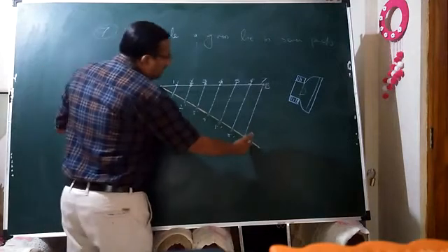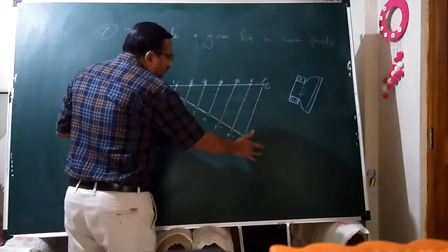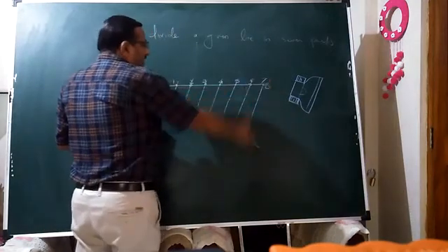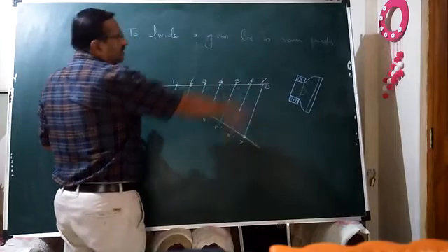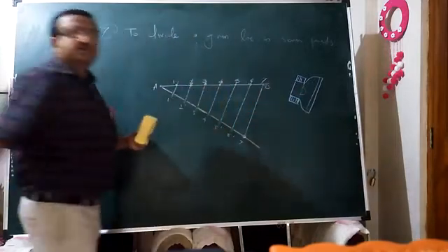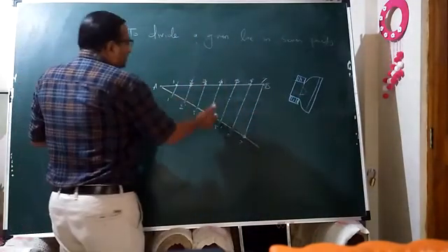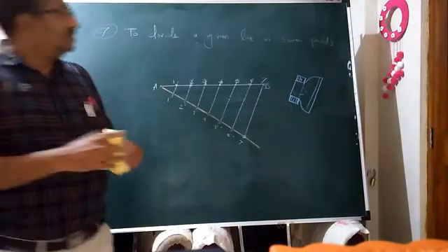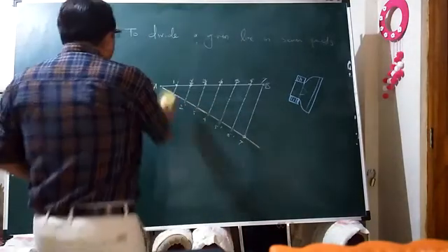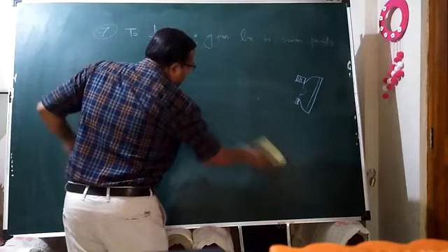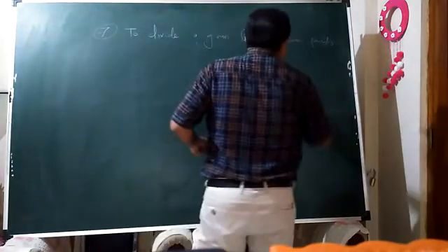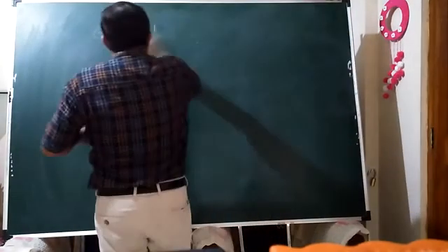And the 11th segment's last point, you have to connect with B and go on stretching the parallel lines by using the same instrument, roll and draw. So it will ultimately yield 11 equal parts of the given line AB. The procedure is the same for any number of equal parts of the given line.